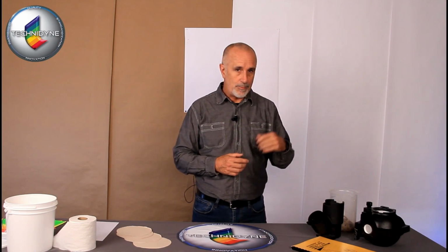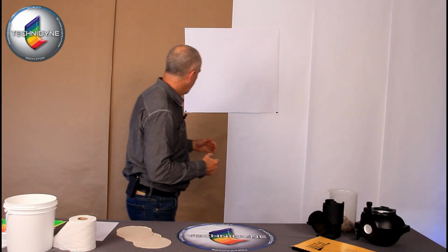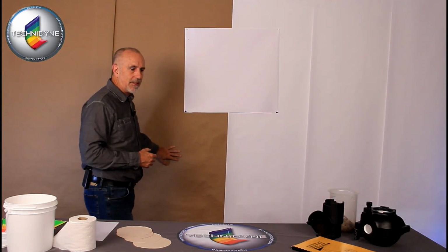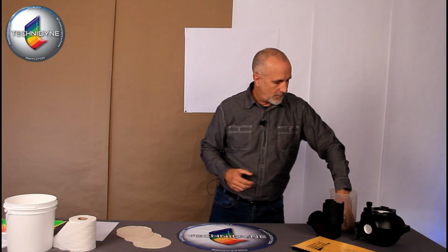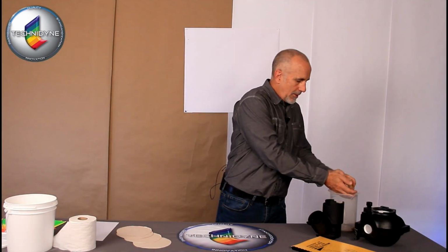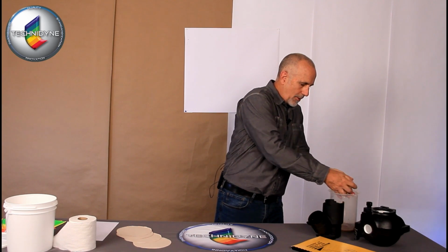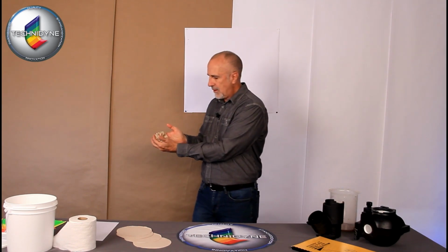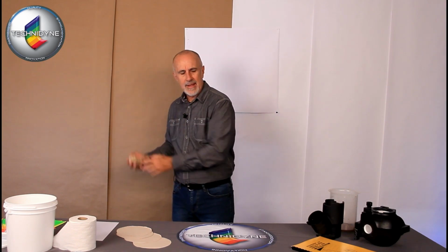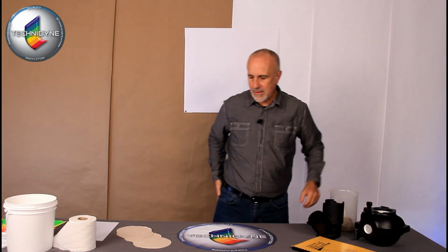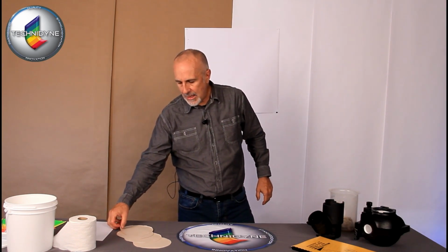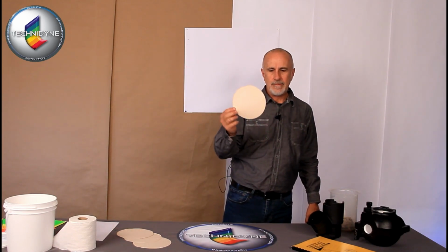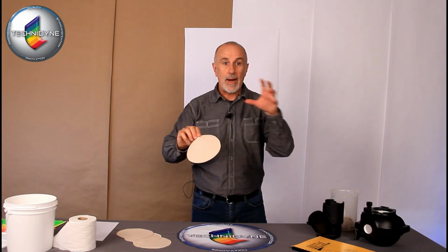One of the things we're going to do is pulp the fiber up. When we pulp the fiber up, it's going to be a dark brown, something in this area here. So there might be some pulp fiber that has a dark brown cast to it. We'll take that and make a hand sheet out of it, put that hand sheet on the instrument, measure it, and get a brightness number from that.